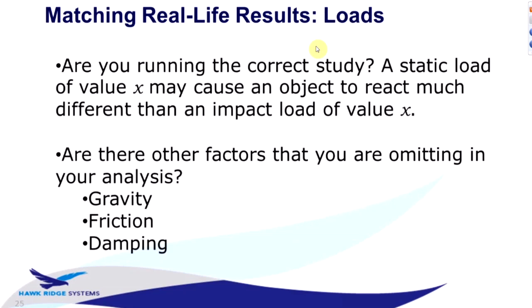Loading conditions, of course, are very important too. One of the main things you should ask yourself is, are you even running the correct study in the first place? Remember that the static analysis, which we've been talking about since last Tuesday, has a number of assumptions built right into it. For example, small deflections and the fact that the loading conditions are more or less constant.